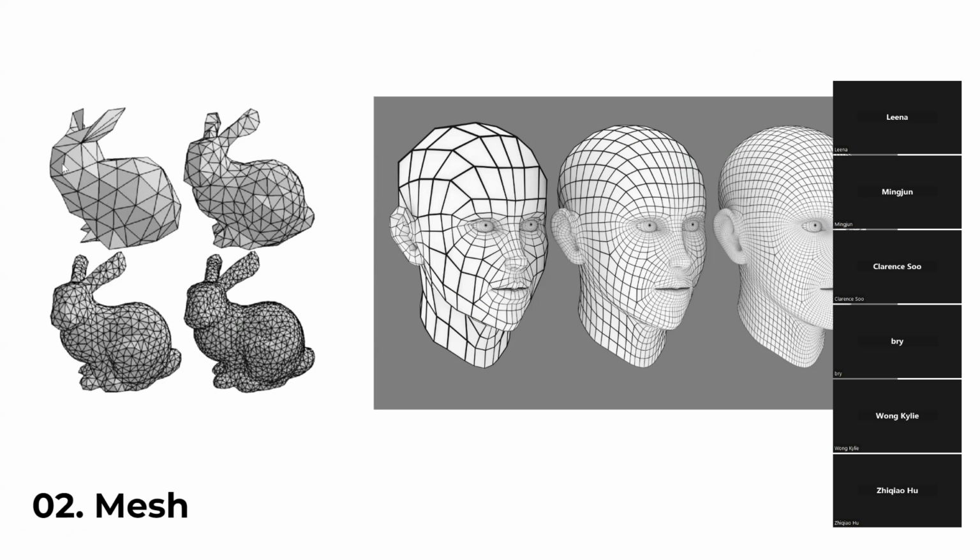If it's fewer meshes, it will be more arbitrary. In Rhino, you can control the amount of planes that you want in your mesh. The same goes for this. If you see this object, the left would be fewer meshes, and then it goes to more meshes.